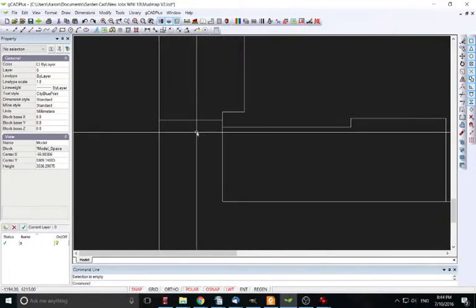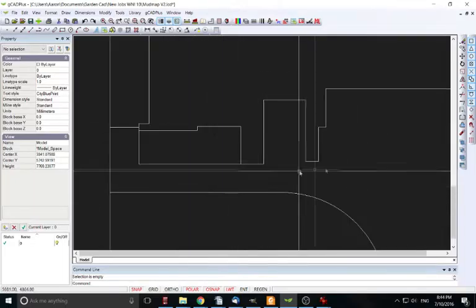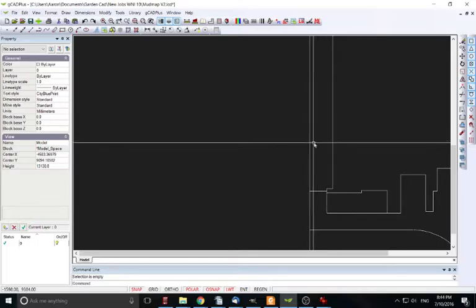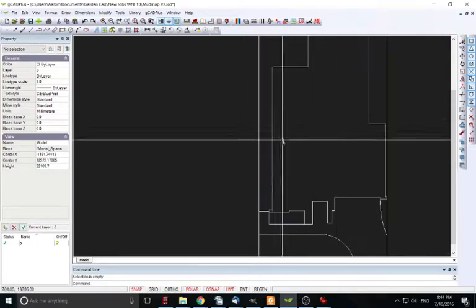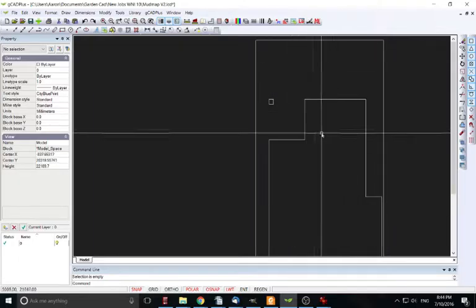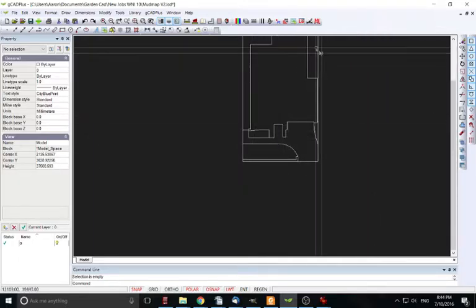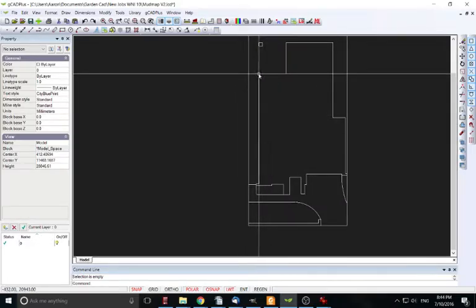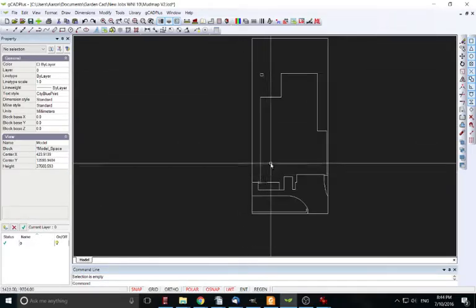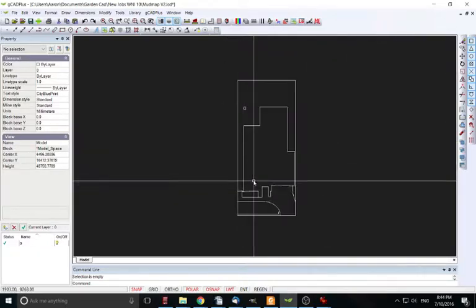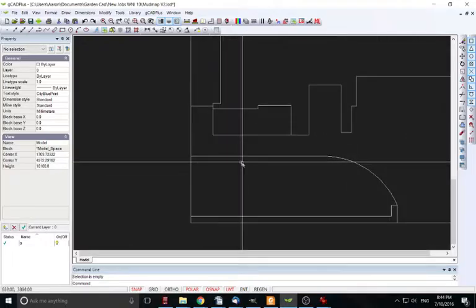Concrete links. What we're going to do is probably do more expensive concrete through here, which is the exposed aggregate, and then down the side we're just going to use a stipple effect charcoal concrete just to reduce costs a bit. It's quite a bit of area through here, and we might do the same for this side, and then just pave back here. And there's no need putting exposed aggregate down these sideways. Sometimes it's preferable to put something like Lilydale toppings or granitic sand down here, but some people don't like it. If you've got wooden floors, you might drag a little bit of the gritty stuff inside, and it can frustrate people a lot.